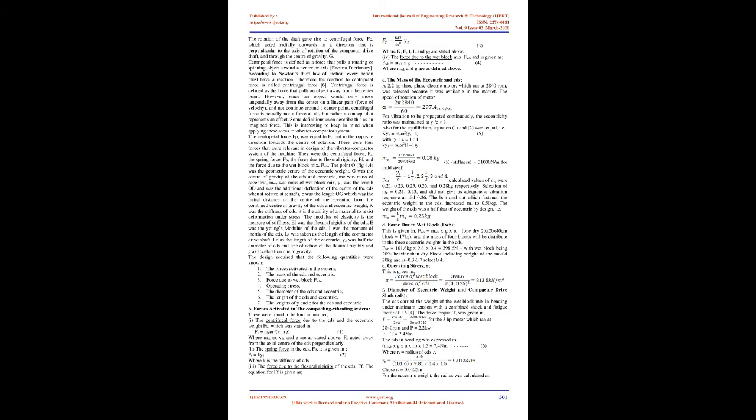There were 4 forces that were relevant in the design of the vibrator compactor system of the machine. They were the centrifugal force, Fc, the spring force, Fs, the force due to flexural rigidity, Ff, and the force due to the wet block mix, Fwb.